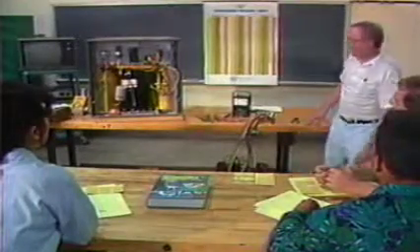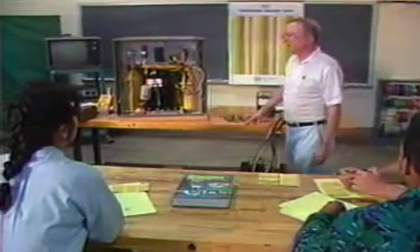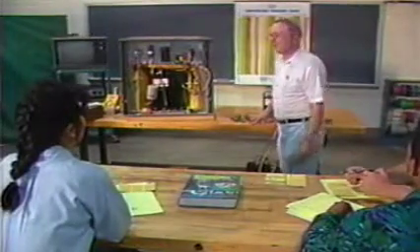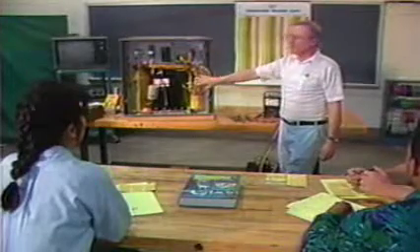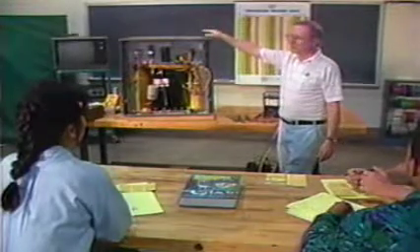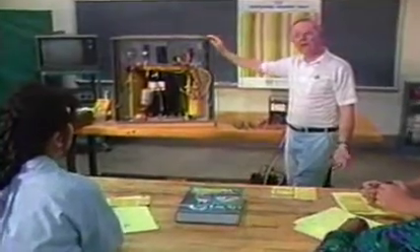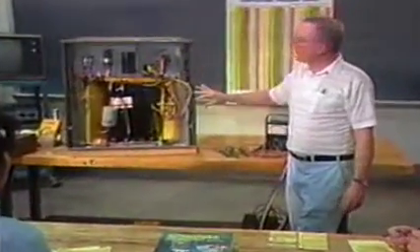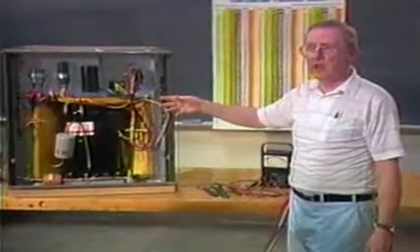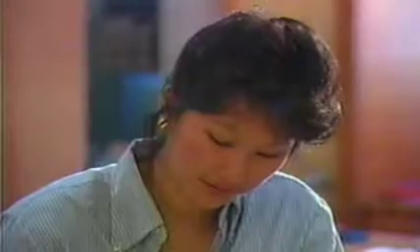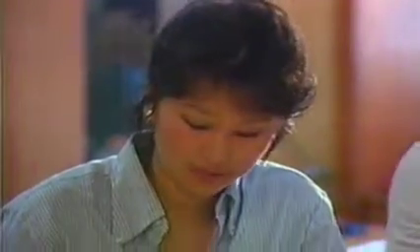We oftentimes find when we're troubleshooting mechanical problems that we get into electrical troubleshooting also. After all, what controls the unit? Electricity. What stops and starts the compressor? What stops and starts the fan motor? Electricity. When we have a mechanical failure, electrical components are what would cut this unit off to save the unit as safety controls.